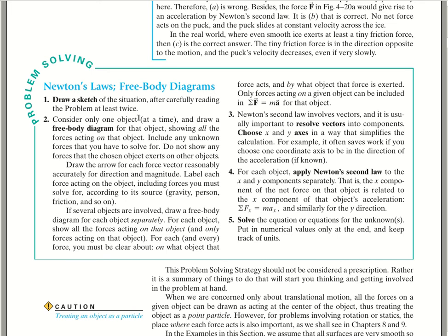So always you have to draw a sketch, the free body diagram, that shows all the forces acting on that object. Forces doesn't mean velocity or something like that. No, any force or acceleration. Then you resolve the vectors, picking the x and y axes, so you work in components, and you use Newton's second law for each object. And finally you solve the problem.